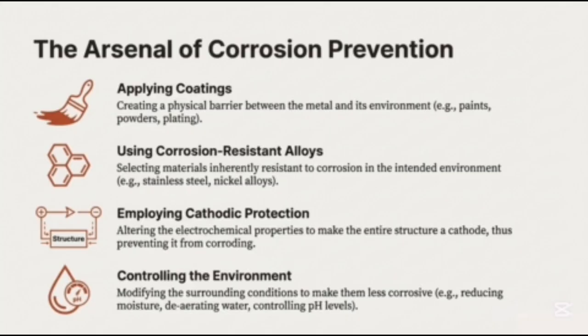When the exchange process occurs between the anode and cathode of the original material, it does not take the electrons from the original material, but rather from the material placed to protect it. Thus, the material placed to protect is damaged, while the material to be protected remains intact.